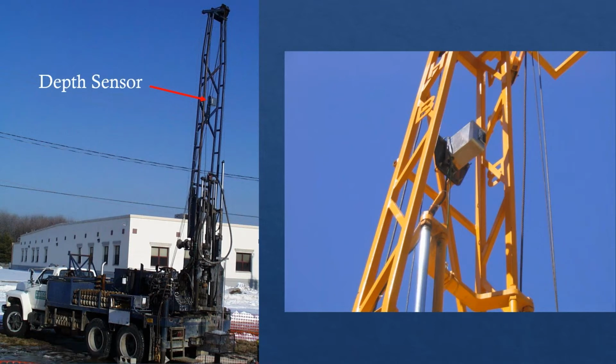And it only records past the maximum previous depth, so it doesn't keep recording when you go up and down with the rod. It just measures all of the new penetration. And that's why when you're done with penetration of one rod, the driller will hit that driller's button and say, okay, now we've added one more rod, so we can keep adding to the depth at that point.